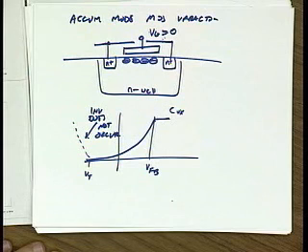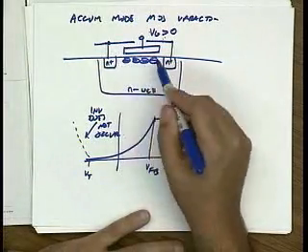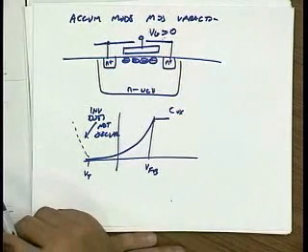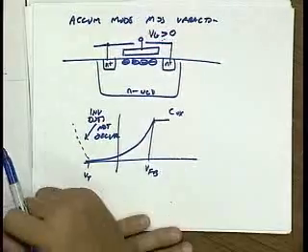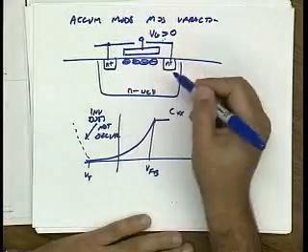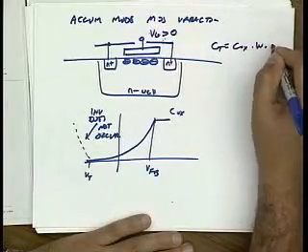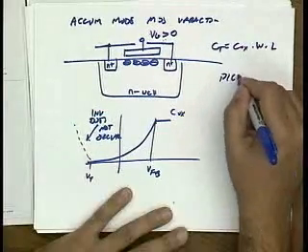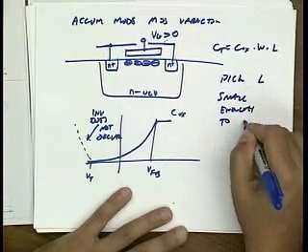Can you comment on the choice of W over L on the effect of the choice on the Q? Yeah, so clearly you want to make L as small as possible because that means that your channel resistance is minimized. But if you use an L min, the layout may become awkward. You might have to have a very large W. So if the Q is already high enough that you can afford to use a larger value of L, you can do it because of course the total capacitance is Cox times W times L. So basically you pick L small enough to get sufficient Q.